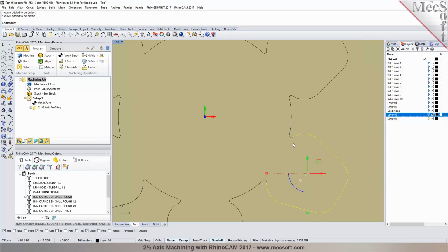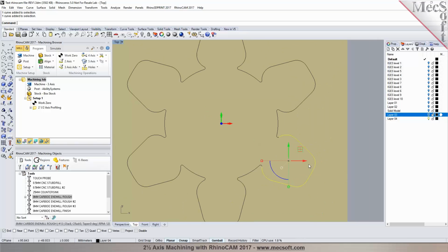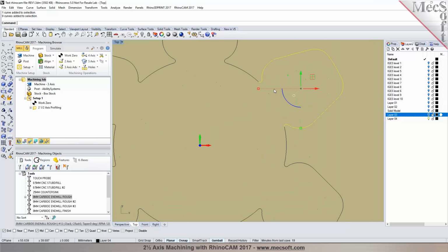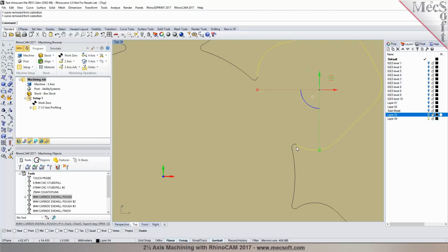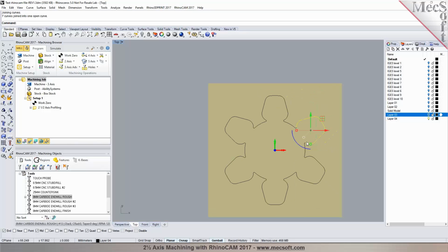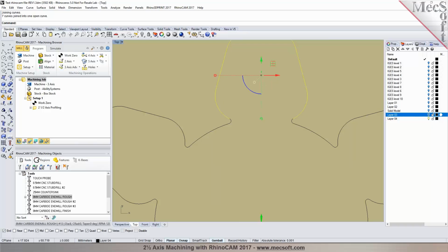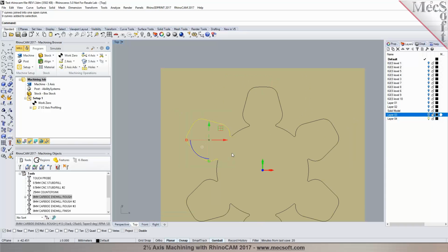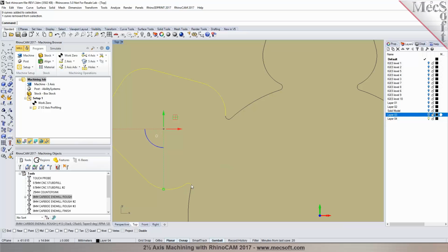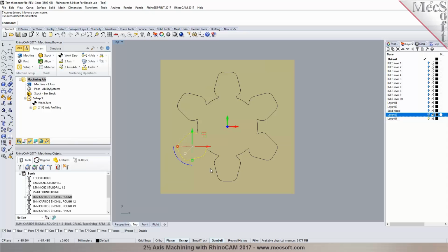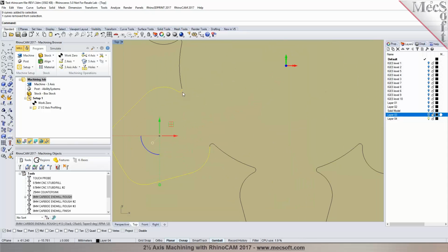Now is this a good section to take a look at? Yeah. Okay, and then I'm going to do the same thing over here and not have these selected right in here. So I'm going to join those. So basically I'm joining them to one curve in Rhino. Just to make our selections easier, I'm going to drag a window to select them, drop these to radius, join them together, and do the same step in here. Select these, drop these to fillets, join them, and repeat the same.